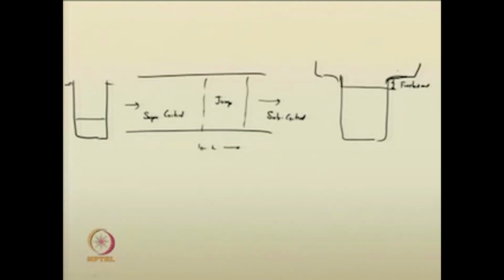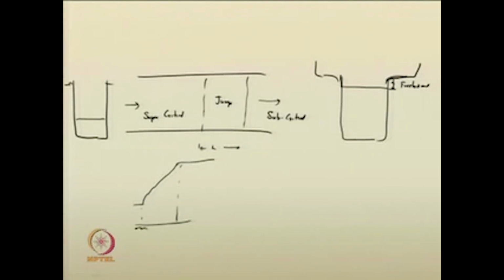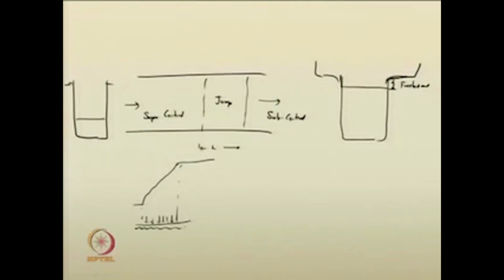Not only that, the profile will also help if you have a profile like this in the channel bed. With respect to the water depth, the pressure will be exerted by the water on the channel bed. Based on the profile, you will be able to evaluate the pressure force, and that pressure force will be used in the structural design or the material design of the channel beds, both for the sides of the channel as well as the channel bottom.